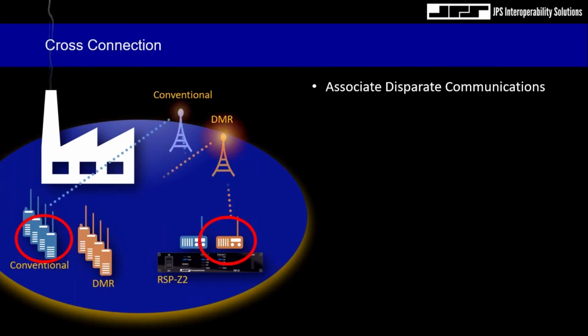So if you key the subscriber unit at the left, you are virtually keying the disparate donor radio at the right, regardless of the frequency, protocol or modulation technique. And if you properly set up the transmit and receive audio gain for unity and adjust the transmit and receive audio delays, you should have completely transparent interoperability.